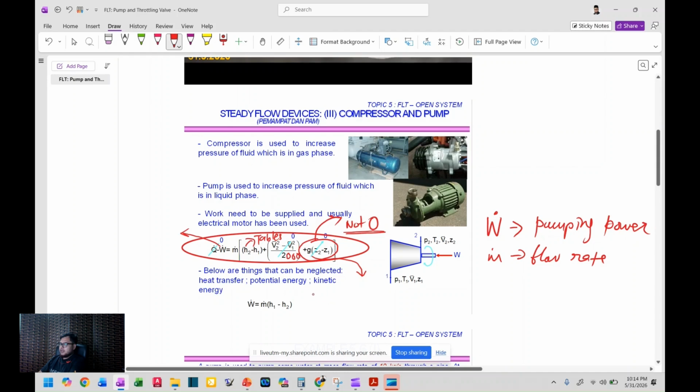Well, last time you had the kinetic energy in meters squared per second squared. Velocity is in meters per second, and when you square it, it becomes square meter over square seconds. You convert that to kilojoules per kilogram by multiplying by 1 over 1000. So that is the conversion.